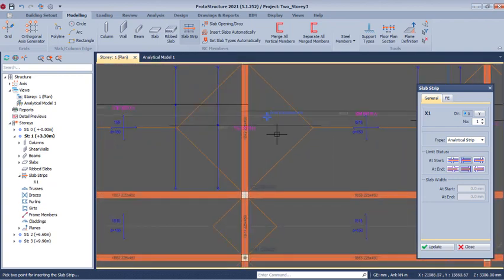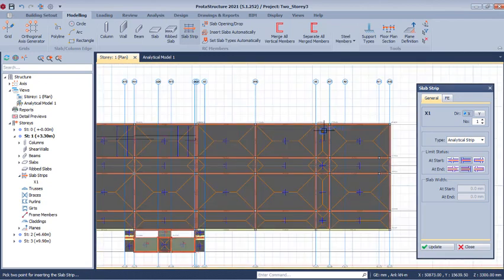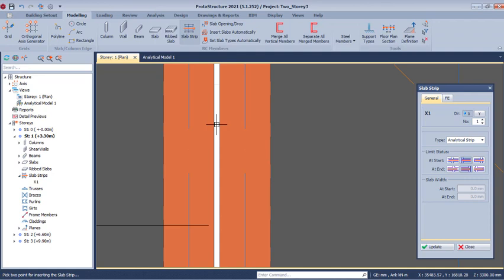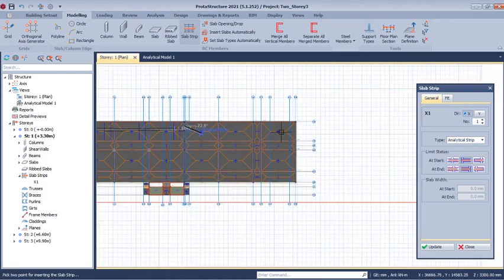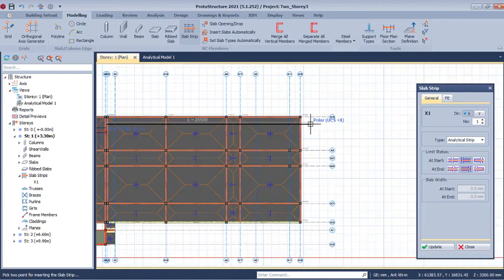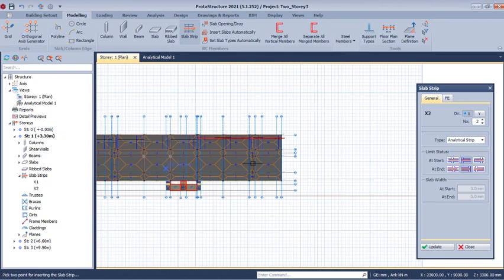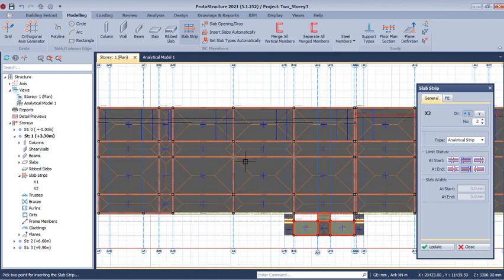You can see the strips. The same thing we'll draw the other way around. Zoom in closely and make sure you pick right between this expansion joint. This is 25 millimeters, a very tiny expansion joint space. Come over to this side, hold the control key to have a straight line, and click on that point to have the strip drawn in this particular panel of the slab. The same thing you are going to do in this horizontal axis for all of these panels.